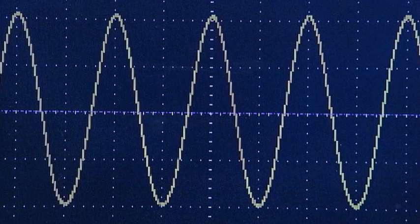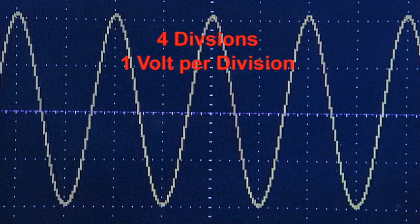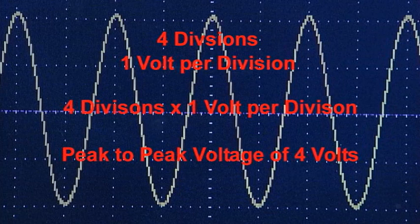The peak-to-peak voltage can also be measured. This is the voltage that is covered from the minimum to the maximum of the waveform. The number of divisions covered is 4. The number of volts per division is 1. Therefore, the peak-to-peak voltage is 4 volts.